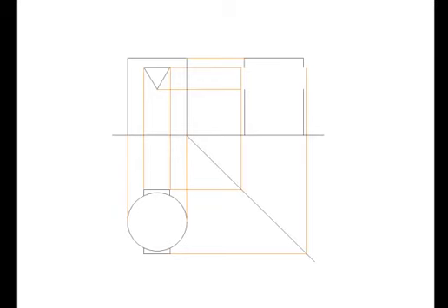As we have the height line from the end view, which was given to us by the elevation, we can draw in heavy. Now we take our first horizontal cut, as seen by the purple line. This purple line cuts the prism in 2 places, which is here and here.